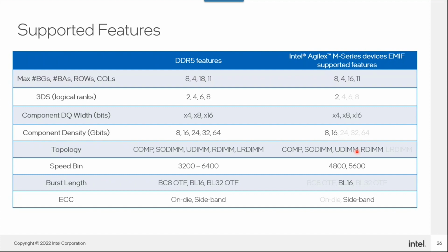So if you have your 2 interfaces overlapping an IO bank, you might run into some fitter issues. As I said, I need to see the exact pin placement, and then I can help you there. When you compile a design with a single instance of memory with the pinouts, it usually does not flag the conflicts that are coming from the other interface placement.